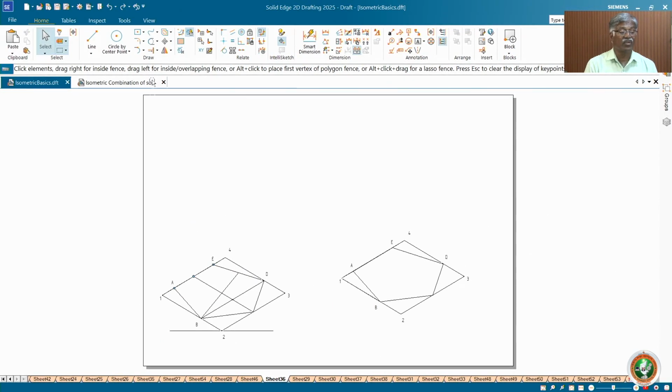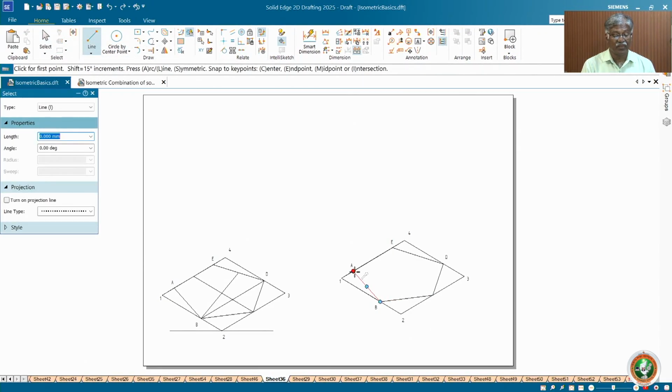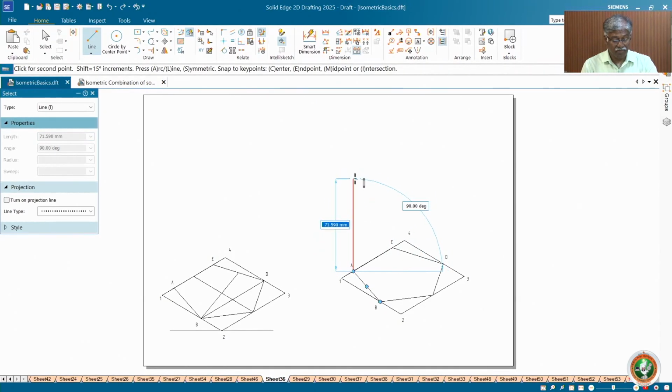Now let me start working on the prism. In that case you have to have the pentagon only. Now let me take this up and create the prism, because the center of the pentagon we don't need in this case. Now let me take this up and create the vertical longer edges, 80 mm say. It may vary as per the demand.